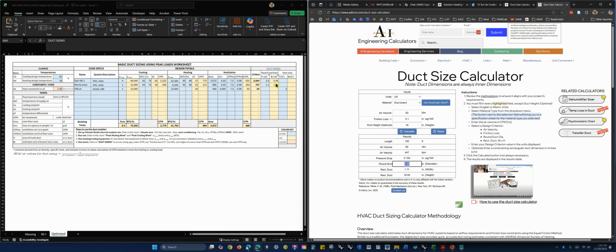So it's a different metric I'm using. I'm not using square feet, I'm using just the diameter, which is what I would look at for a round duct. In this case, I am sizing just the ventilation system, a duct just for the ventilation air. And what's the point here? I may want to try to get all of my zones into this category because maybe I want an exposed ceiling in my beautiful pool or whatever it is you're designing, and I don't want ducts exposed there or behind a plenum. This information helps us understand what kind of system we would want to meet our architectural goals. So that's another reason why we're doing it.